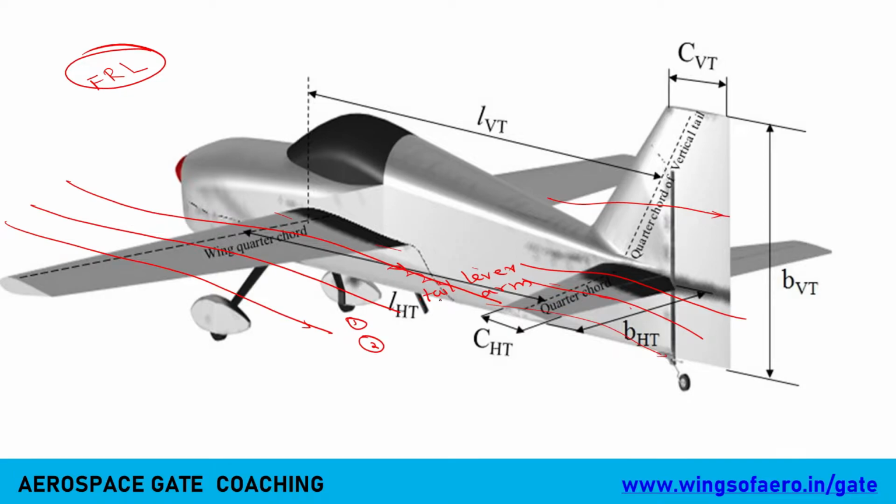The distance of the tail lever arm is very short. For that reason, there are a lot of vortices that interrupt the flow over the horizontal plane. That creates instability for the aircraft. That's why we prefer to use a T-tail configuration for a business jet.